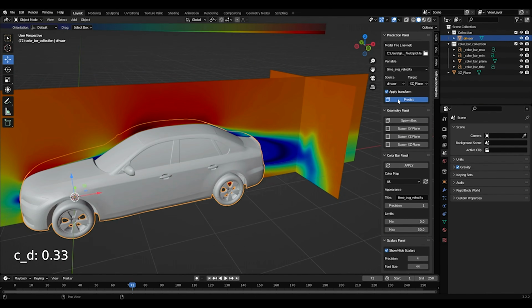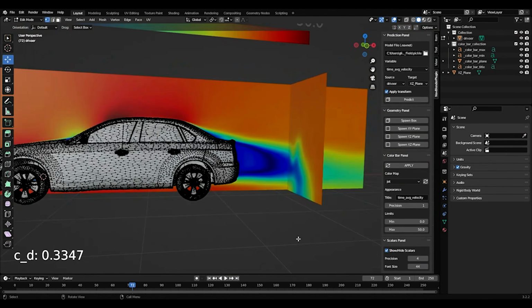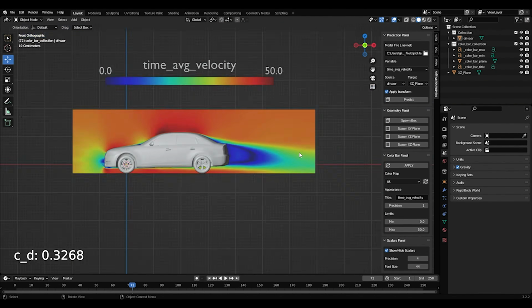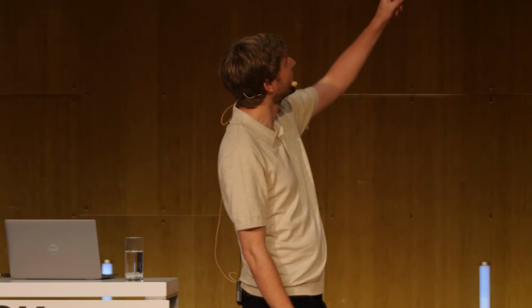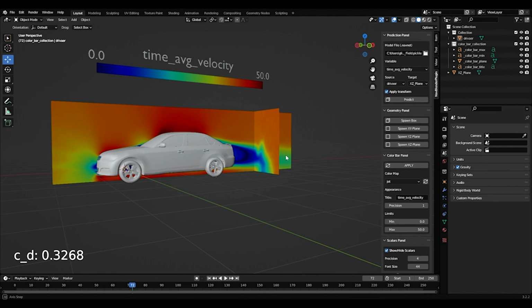Use the information that is already available in your company that uses best practice from the engineering teams. So this knowledge is condensed into the AI model, and then you can simply leverage it to predict those scalar values like drag, lift. You can also predict surface fields, pressure, wall shear stress, temperature, whatsoever. And you can also do some volume predictions. I prefer volume predictions on slices because that's what I look at in the end. I don't like those streamline pictures. As an engineer, it's hard for me to get some information out of it.